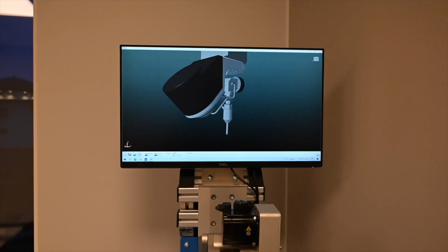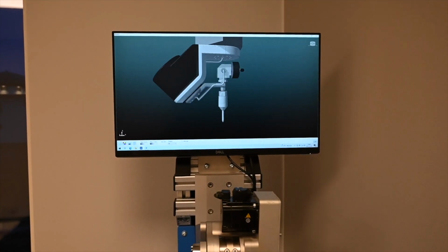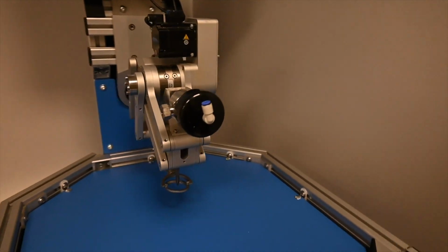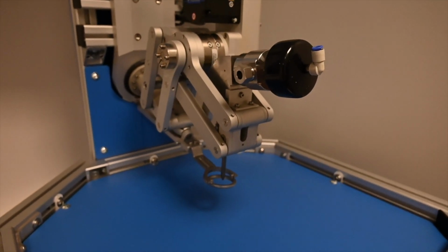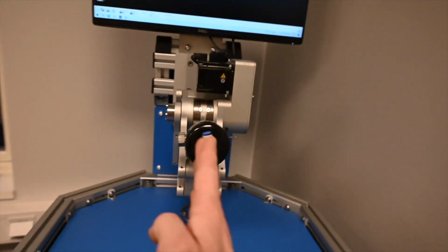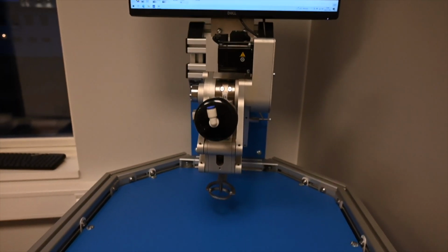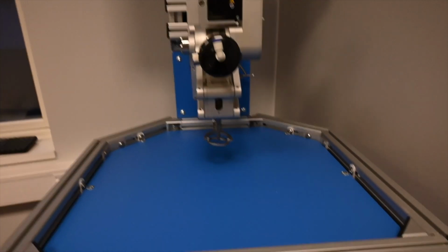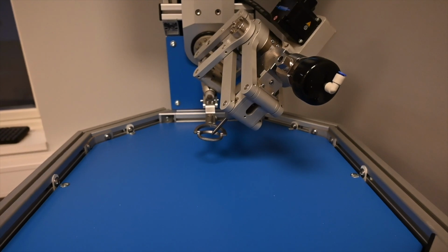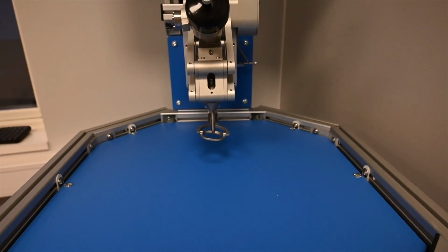I can rotate around my own axis, while this one only rotates a couple of degrees. So that's the power of the tilter. We have small angle movements for taper angle control like this, but we can also go down to 4 to 5 degrees real fast, like that.